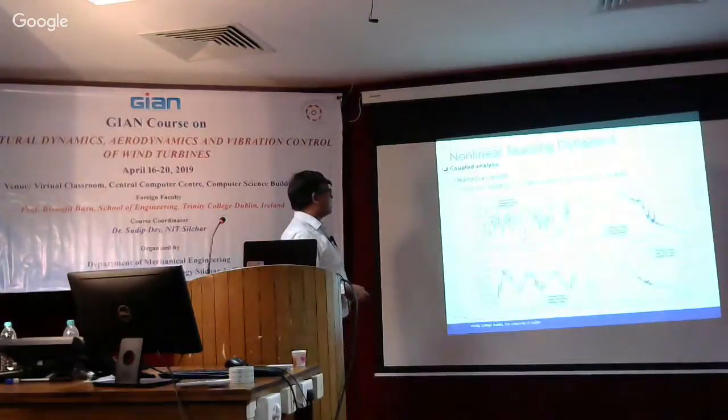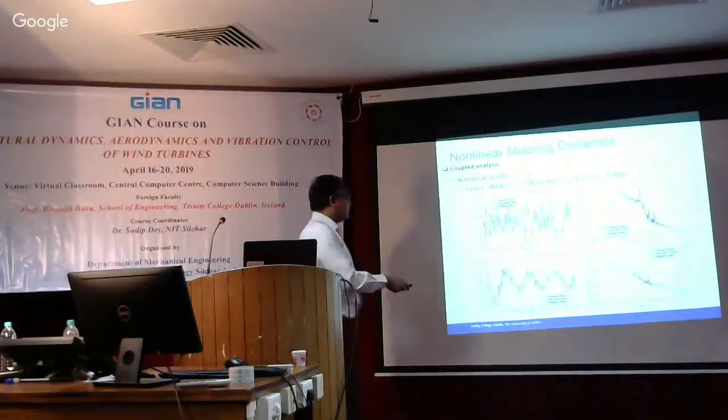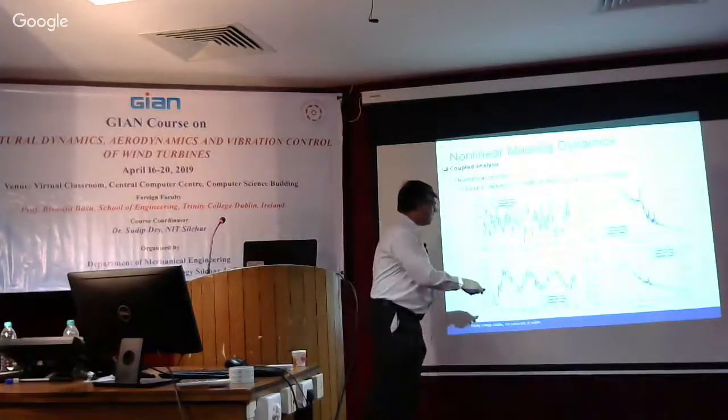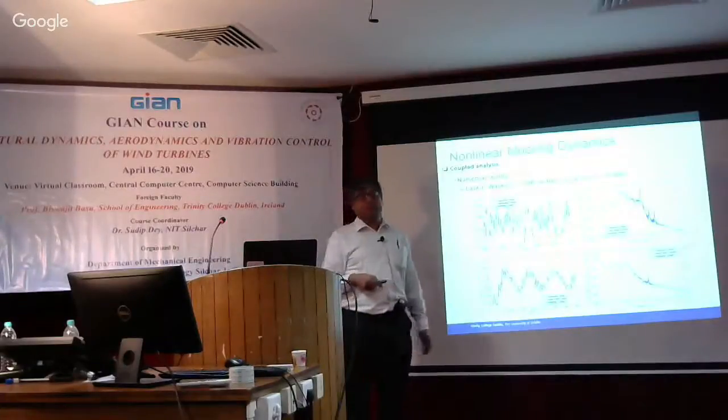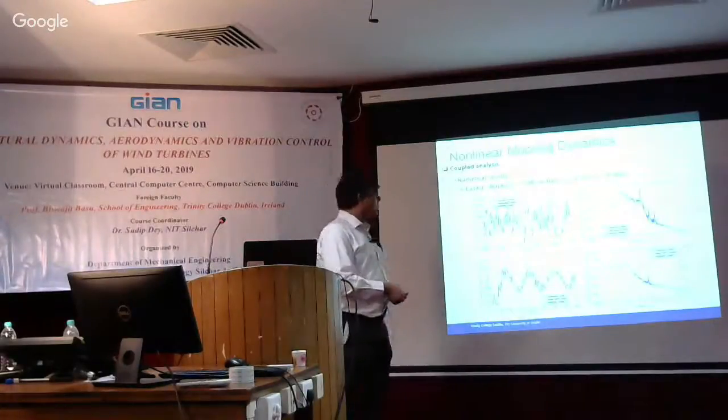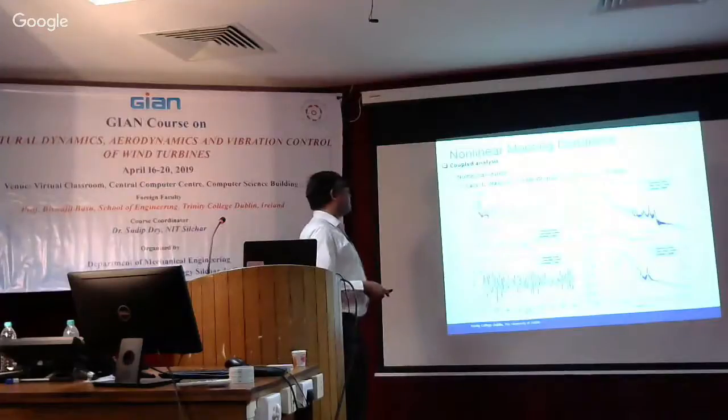And these are some results of the power side and spar and so on. You can see the linearized model and the nonlinear model, how they are changing. In some cases, there's not much difference. When I say linearized, quasi-static, and nonlinear model, this is the mooring model we're talking about. But in some cases, you can see there's a significant difference between the linearized and quasi-static model and the full nonlinear model.